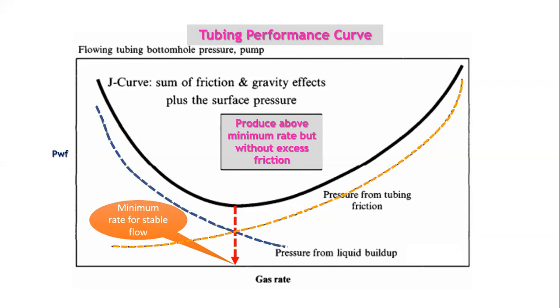The more gas we have, for instance, with the production, the gas from the reservoir is increasing, so the original calculations we made, the gas is changing. Remember that everything subsurface is changing: the pressure is changing, the gas liquid ratio is changing, the GOR is changing.